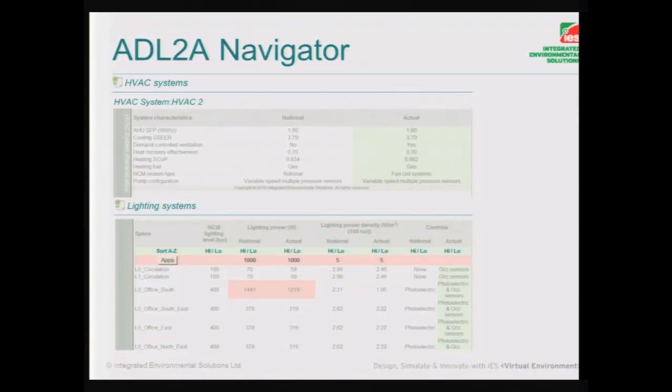So really across the whole range of the notional building's performance, whether it's the fabric settings, infiltration, system efficiencies and controls, we really need to be designing to a very high level, again, just to match up with this. Anywhere where we fall behind that, we're needing to make up that deficit elsewhere. And that's often where, I say, the crash net of renewables comes in. Designers will get towards the end of the project, they'll find that there's little scope for making changes, and they're perhaps forced into putting in some PVs or wind turbines in order to bring their target emission rate down, or their building emission rate down to a compliant level.